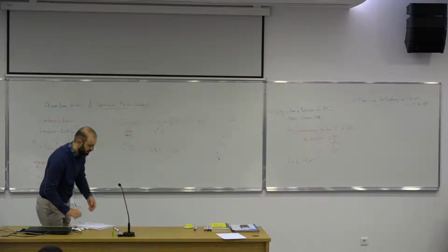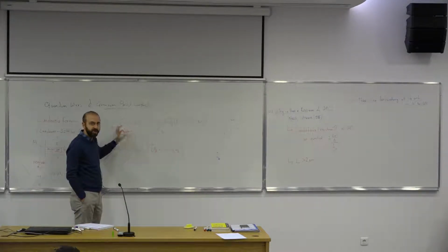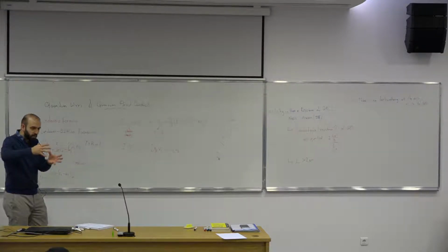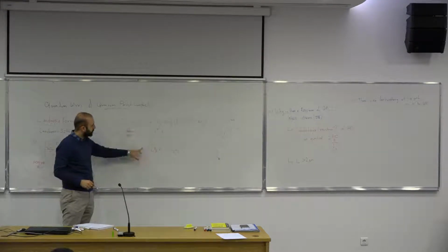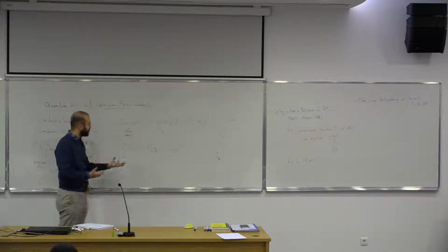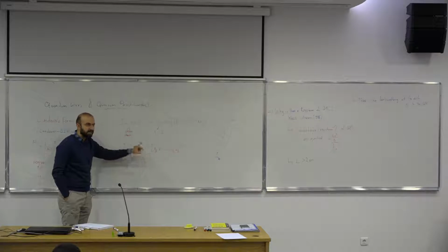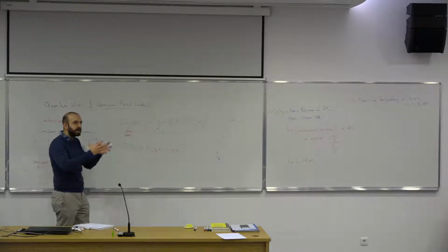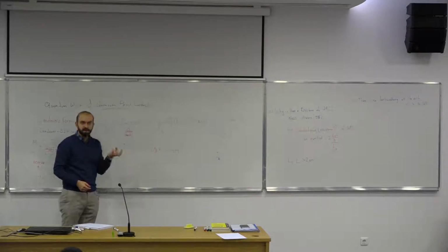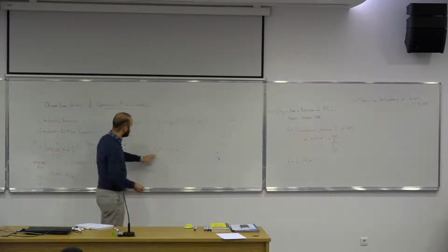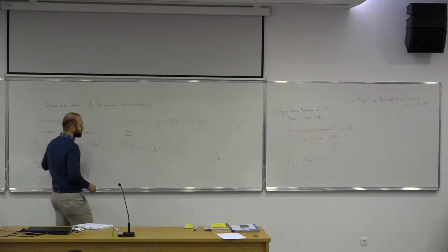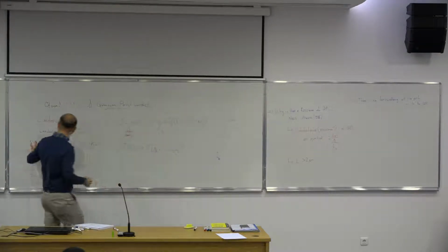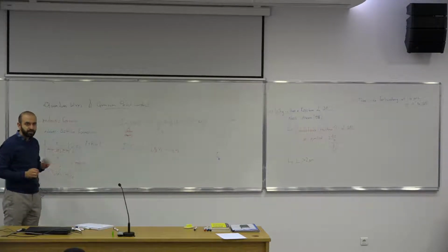So the idea here is, this was sort of the classical expression we had, and the assumption in this expression is that for any current, I take a collection of electrons that are moving with velocity v, but now I should reduce this down to the single electron case. Still, I should be talking about density of electrons, but now I have a very important difference, because the transmission probability when I take this collection of electrons is no longer 1. Rather, it's given by a certain transmission probability, and also the number of electrons on the left-hand side times its velocity, and this difference will give me the amount of electrons that will be transferred from the first side to the second side. Does that make sense?